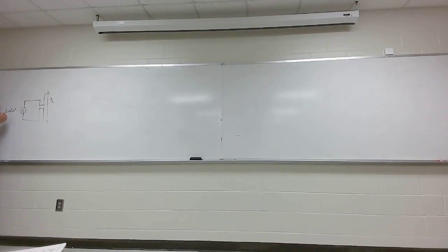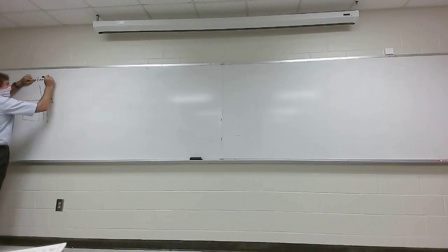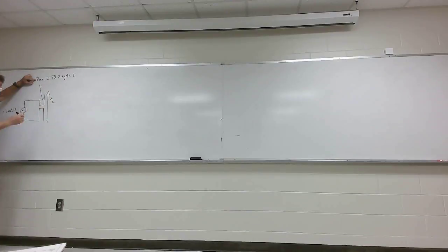So really, this is the magnitude of V at an angle theta sub V here. You think of it that way. This half-wave dipole is an exact half-wave dipole, so the actual Z antenna here is going to be 73.2 plus J 42.5. This is reminiscent of something you saw in your quiz.